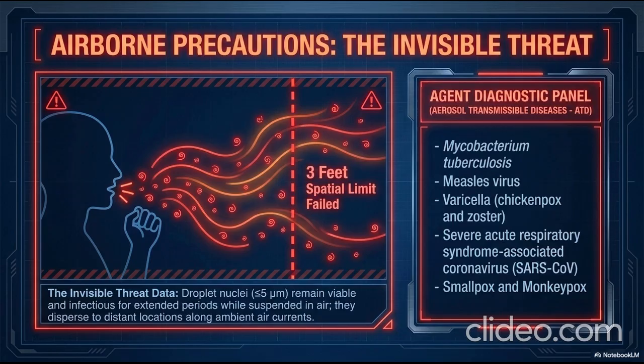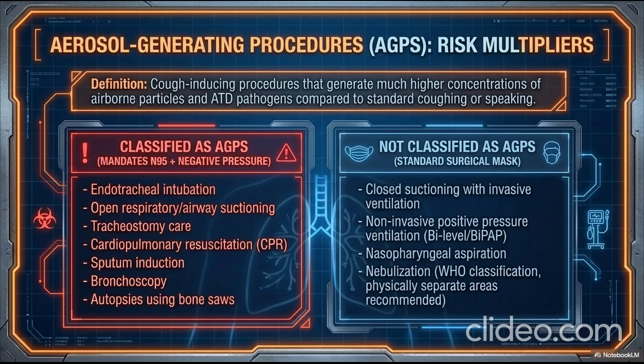Third, precise sealing with a maximum leakage area under the door of 0.5 square feet. Finally, a clean to dirty airflow that ensures air moves from the HCW toward the patient and then directly to the exhaust.